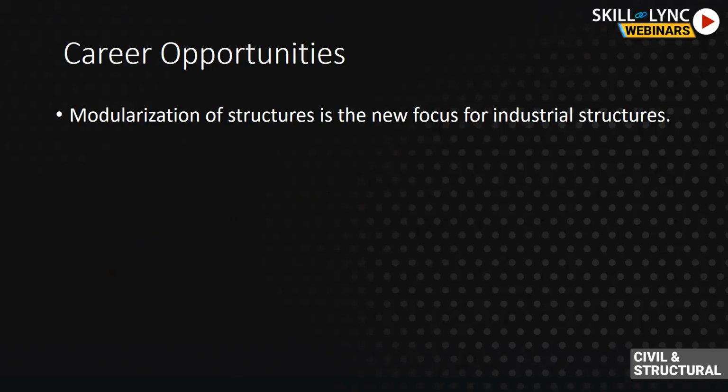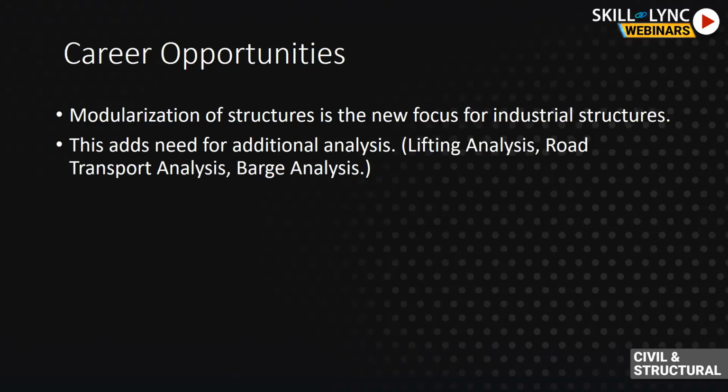This saves a lot of time at the site, and it can result in early completion of the jobs and early startups of the various plants. So it's a very promising field. But modularization adds design challenges within the design office. For the engineers that design the structures, it's an additional work for them because it needs further analysis like the lifting analysis, road transport, and barge analysis, and a module assembled in a yard will have to be lifted and put on a truck and then transported.